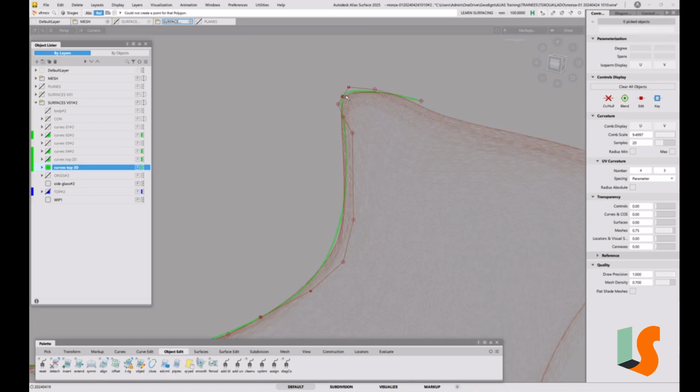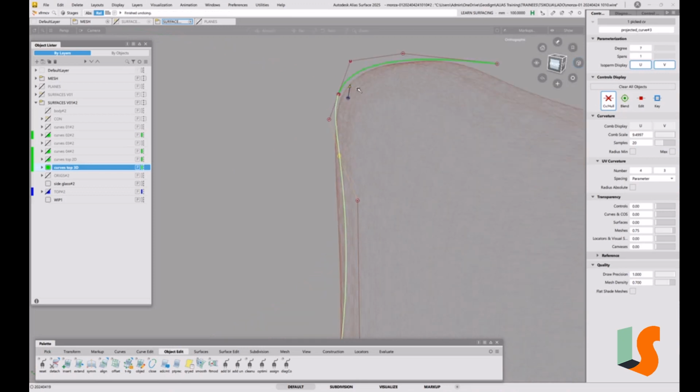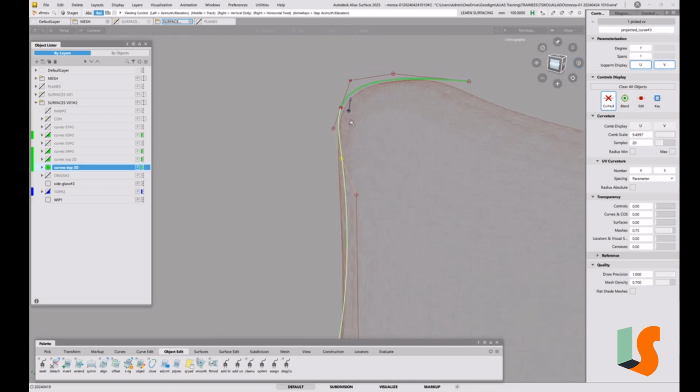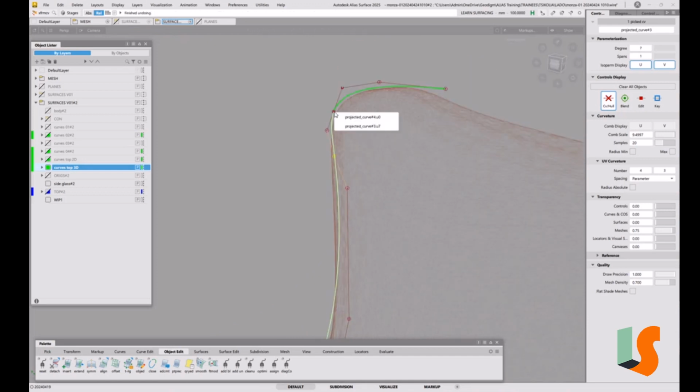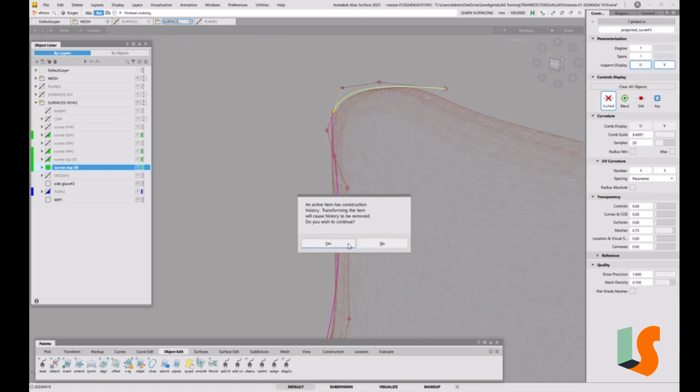Now this is aligned to that. So if I try and change that in the Y direction, okay, sorry, that is the fourth point, so we're okay with that one. It's this one I won't be able to change, so it doesn't want to change in the Y direction because it's aligned to here, so it's completely determined by that curve there. So if I want to move that one outboard, I'm going to have to do some change to the curve at the back.